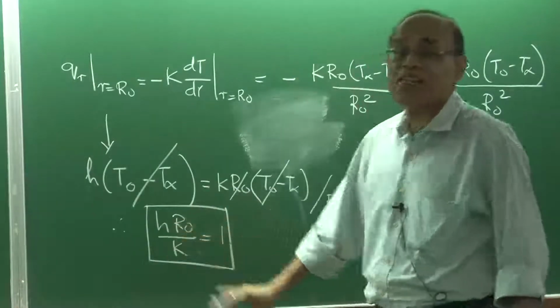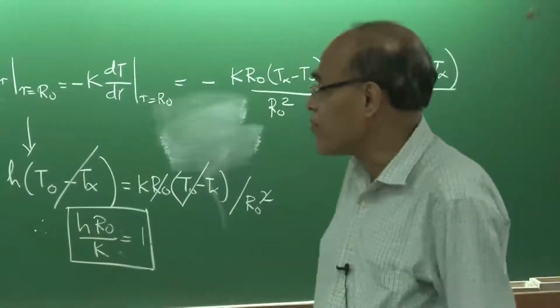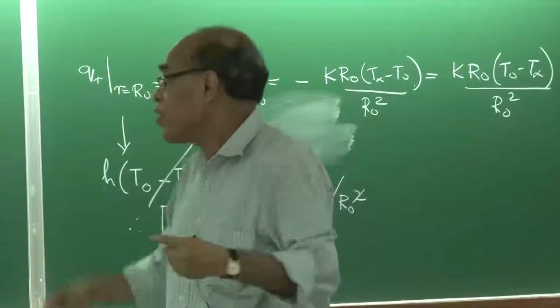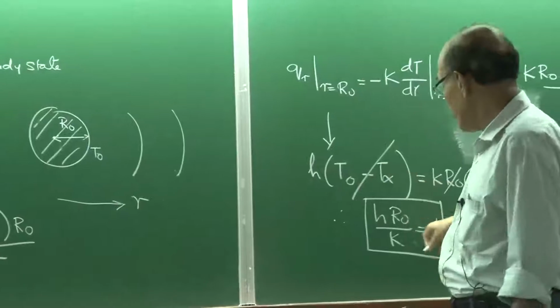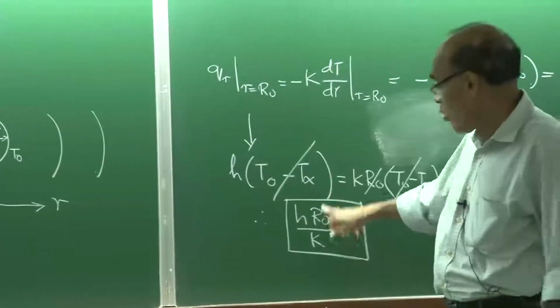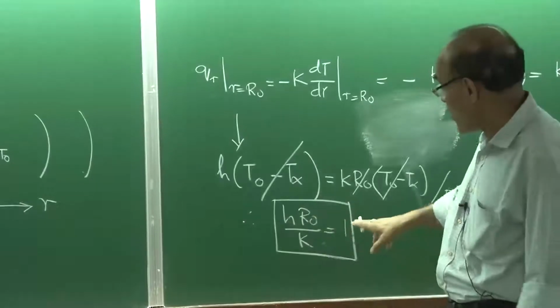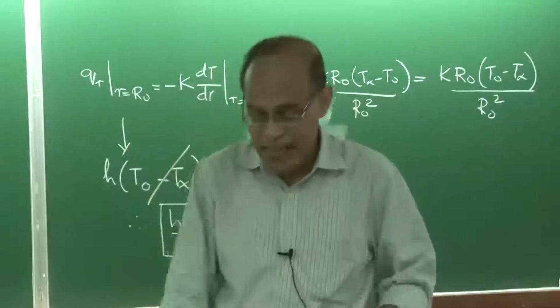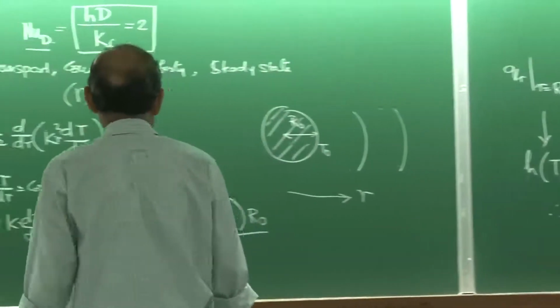So, this number, Nusselt number, basically tells us that it is the ratio between convective to conductive heat transfer. That means in a convection dominated system, had there been a strong current here, the value would have been much greater than 1, because the numerator would have been significantly larger, but the value is 1. This is the limiting value possible, a pure diffusion case or pure heat conduction case, when there is no fluid flow present in the system.